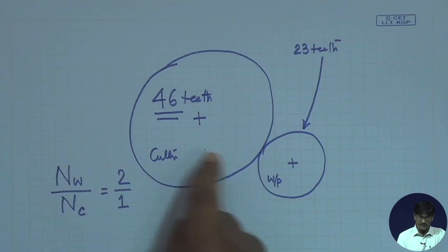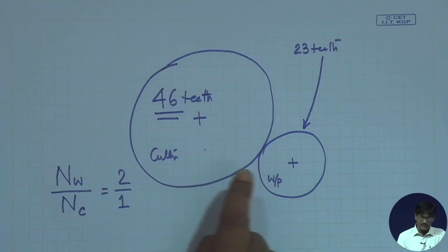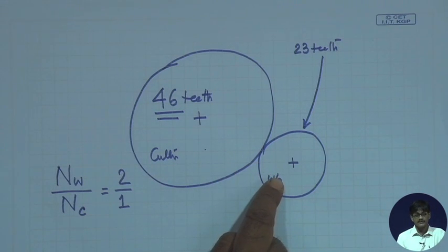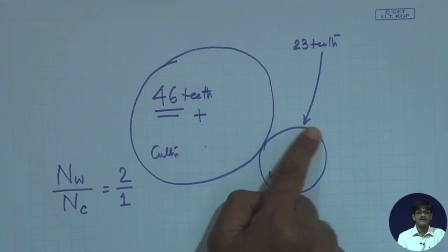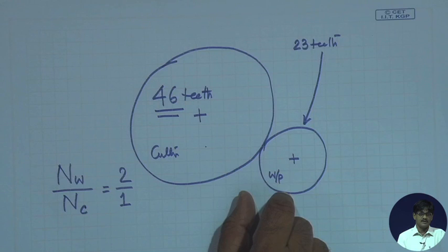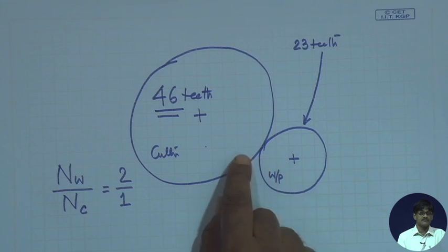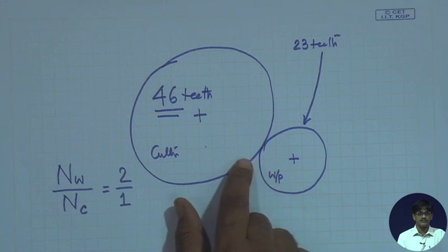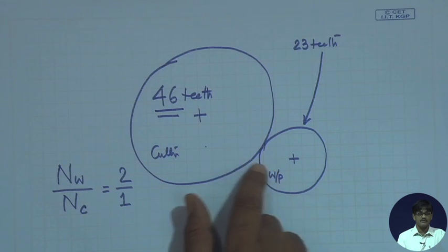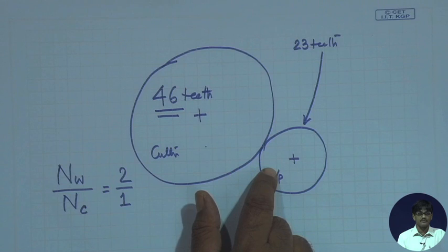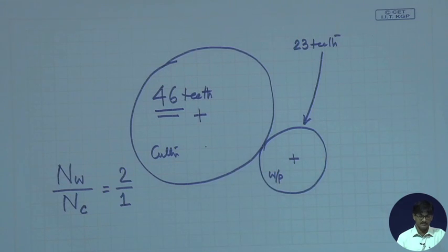If you set a definite ratio, accordingly a particular number of teeth will be machined on the workpiece, provided we provide the workpiece with a blank with the correct outside diameter. If you provide a wrong diameter, something will go wrong, and rubbing will take place between the cutter and the workpiece, which will ultimately spoil the teeth.